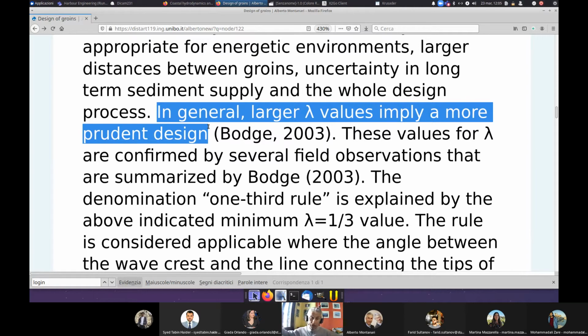You reconstruct the dune, because keep in mind, on the Adriatic Sea the dune was removed in order to facilitate tourism. But the dune is an excellent protection against erosion. So they say, okay, when there are no tourists, let's build the dune again. What is the problem with this solution? The problem is that by moving sand, you destroy the ecosystem.